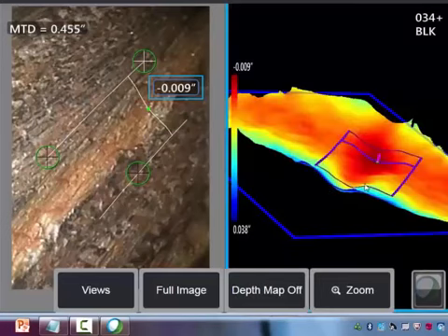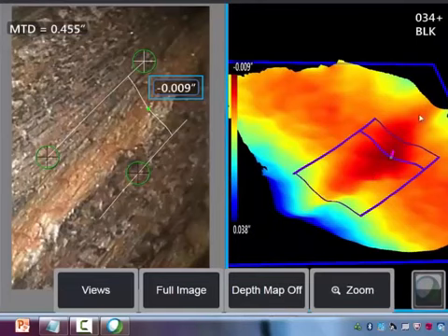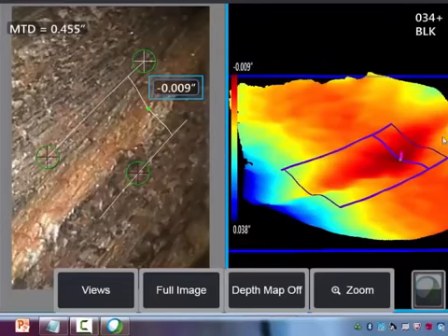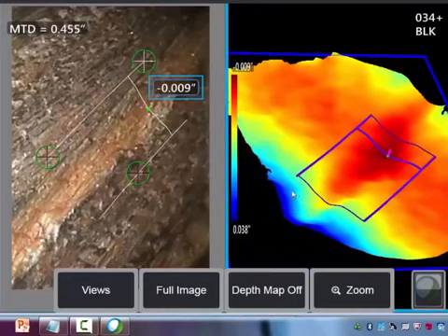When we turn on the depth map, we see a nice clean signature of this indication showing up in this area, and the noise outside of the indication region is quite low. So this is really what we want to see when we're making these small depth measurements. So, in summary, if you're making small measurements, especially of a depth type, you want to get as close to the target as possible, and you want to be sure to check your point cloud for noise bumps that might be degrading the accuracy of your result.